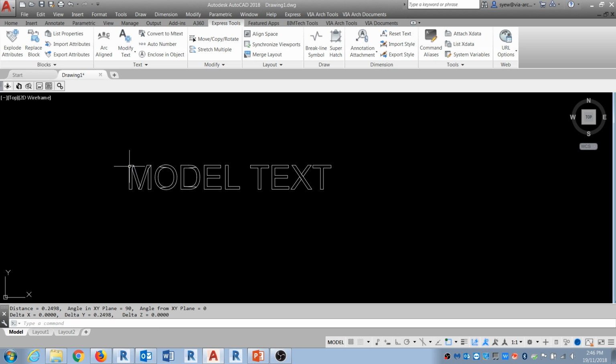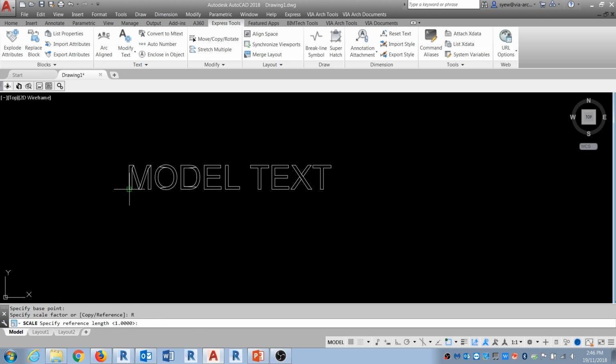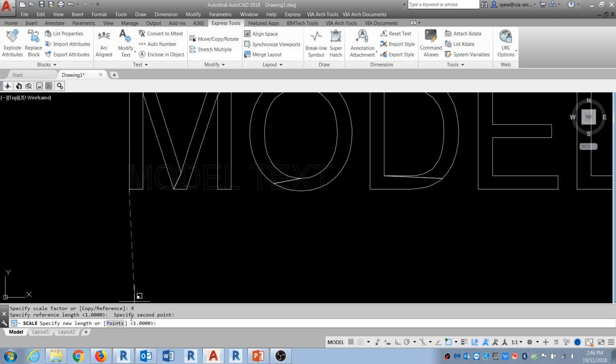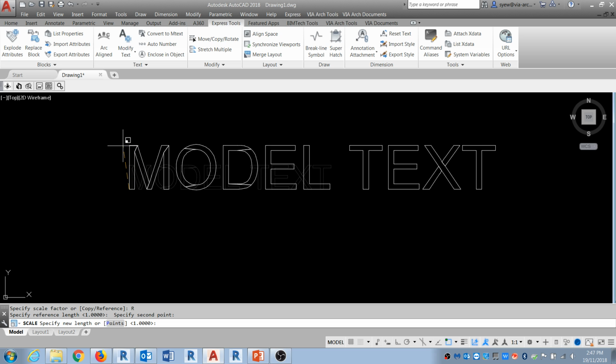If you want to do signage, in my previous job we had to create some sort of elevator mosaic, kind of an elevator push-pull button kind of thing. What tends to happen is that when you start using a smaller model text size for those, it will lose that information. So what I had to do was physically create a text inside AutoCAD and explode it so that I get the proper text.